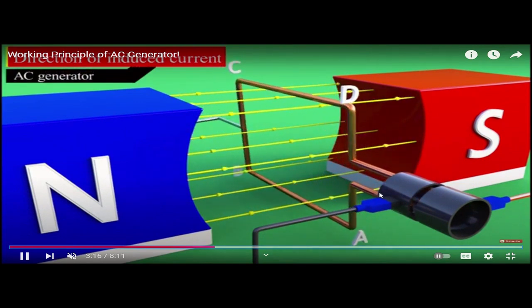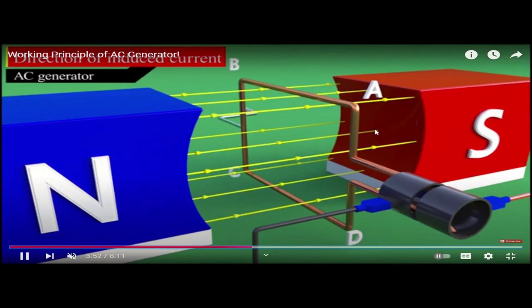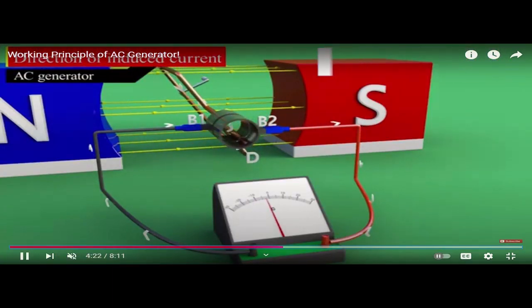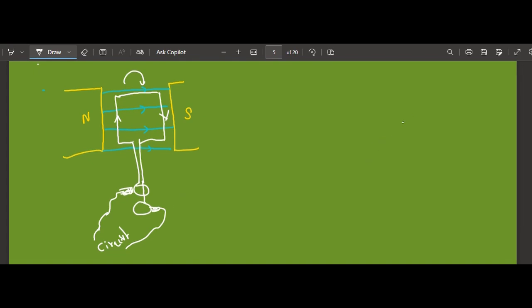So why do we need these rings? That is because if we go back to the board and you just connect the ring to the circuit, a bulb or whatever device we are connected to, what will happen when the coil starts to rotate is that the wires get entangled. They will be twisted and the circuit will be broken. To avoid that, we have to use these two rings.